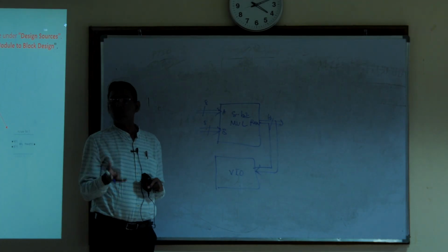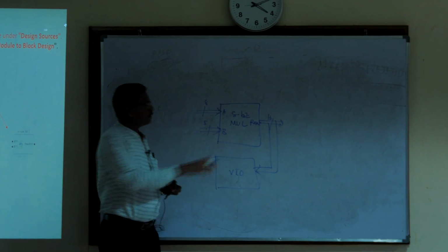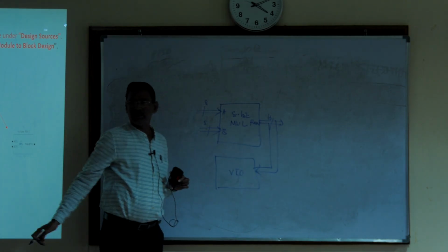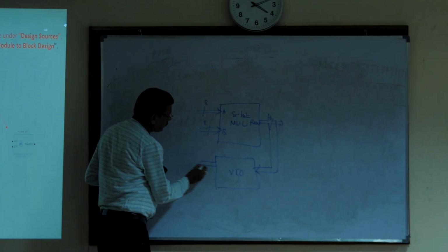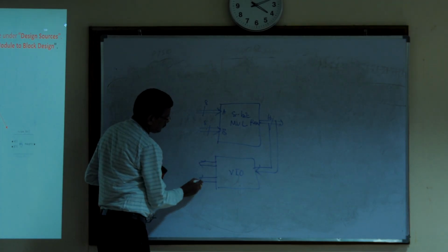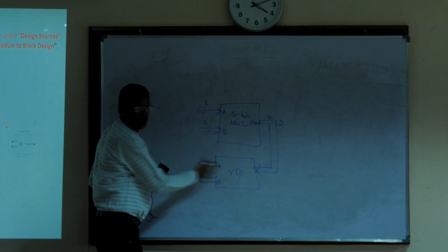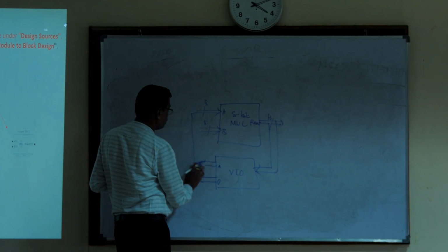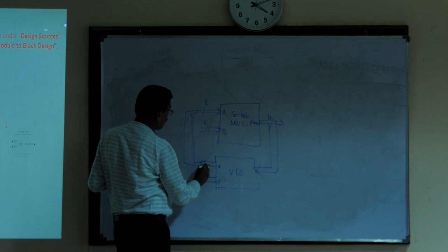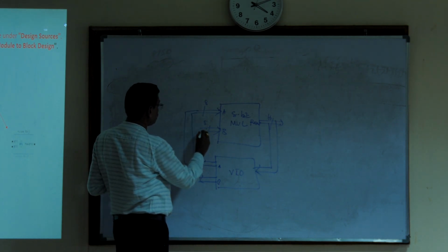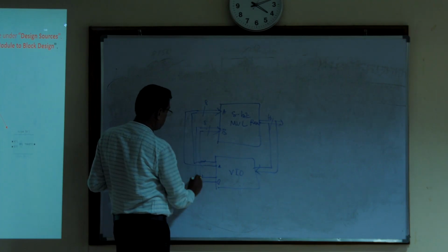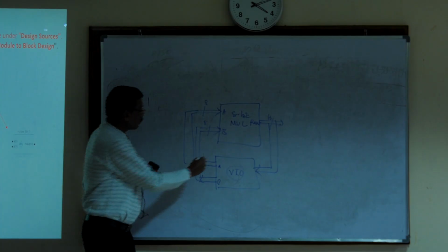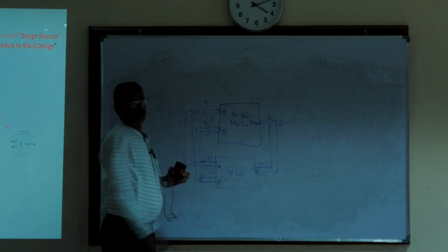This is virtual input output testing. That's why the output of this you have to connect as input to this. And here it has to generate 2 outputs, A and B, which will be connected to the multiplier inputs. So this VIO should generate 2 output ports and 1 input.